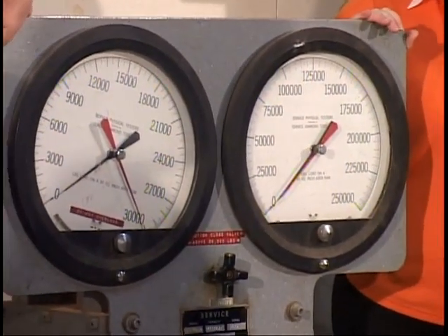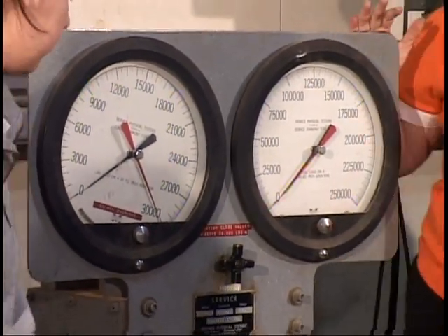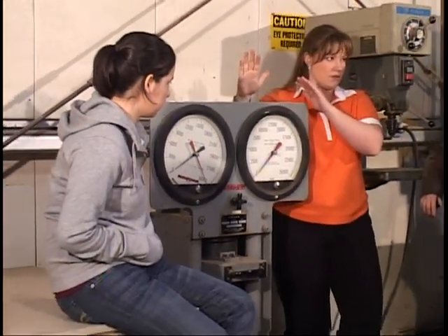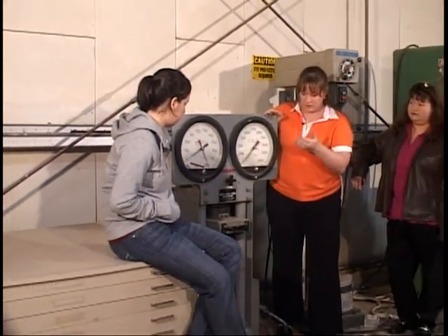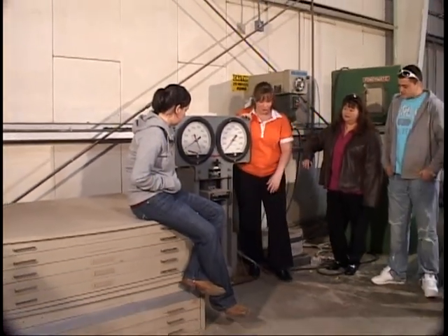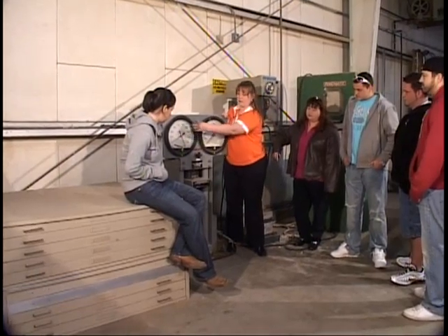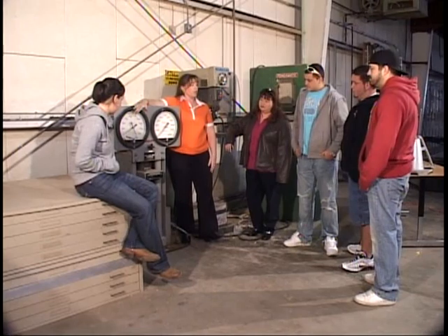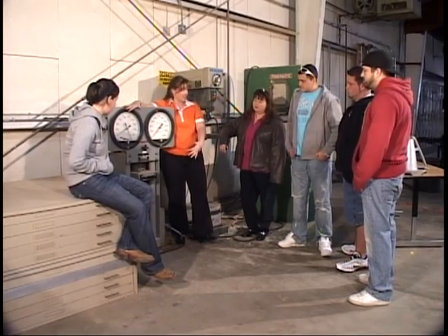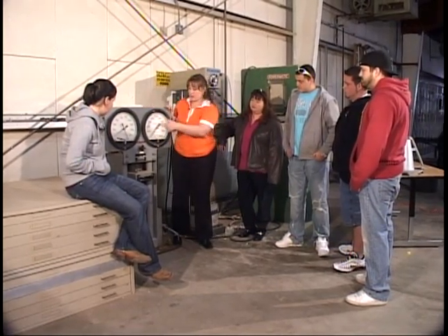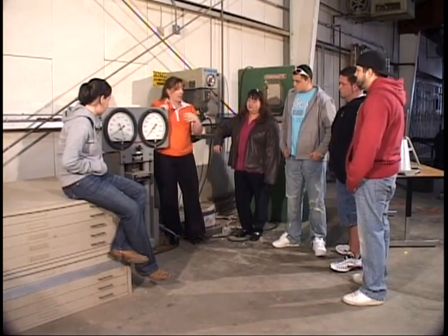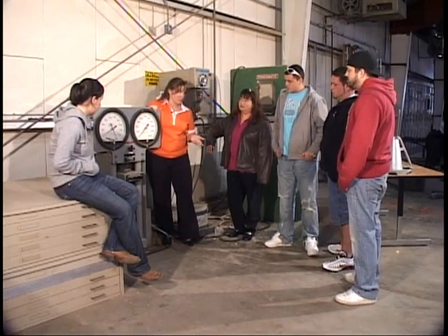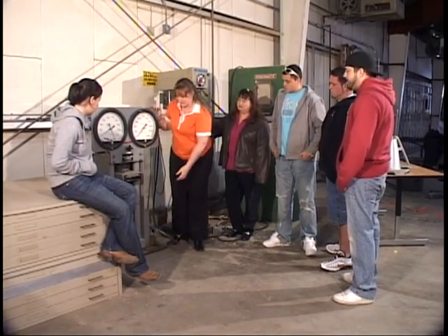Okay, I'm rolling. So for concrete class today, what we are going to do is find the compressive strength of a concrete cylinder, and that's what this machine will help us do. So we have our cylinder in place. We're going to start applying the pressure, and it's going to be read on this dial. This one can go up to 30,000 pounds, and believe it or not, it's going to take more than that to break the cylinder. Once we get the total amount of force applied, we'll divide that by the area of the cross section, and that'll give us our total strength in pounds per square inch. So let's get started.